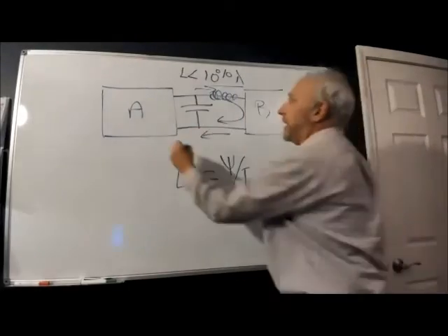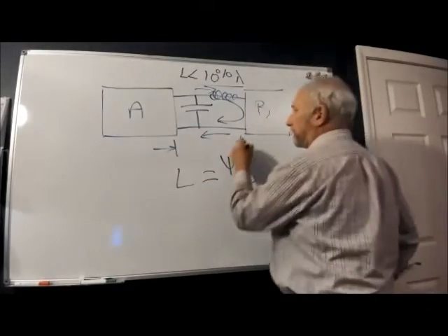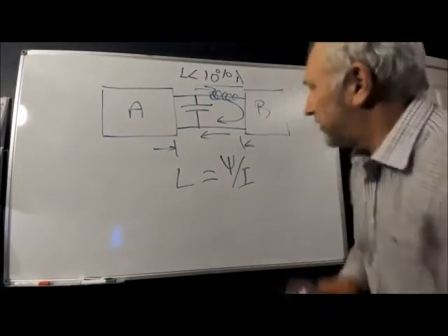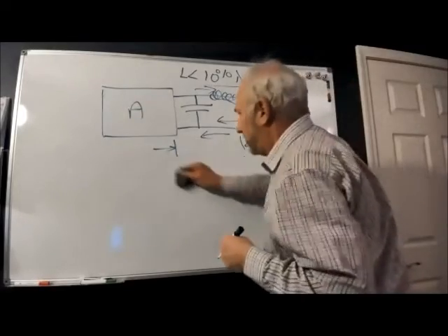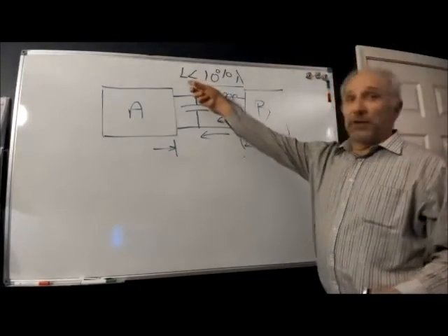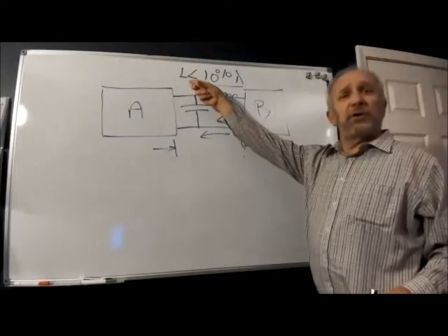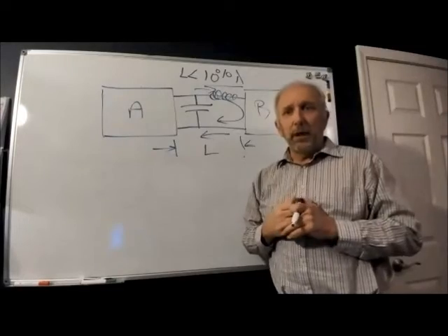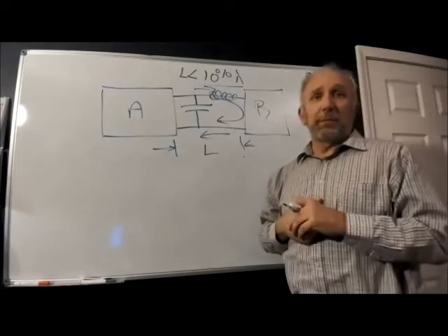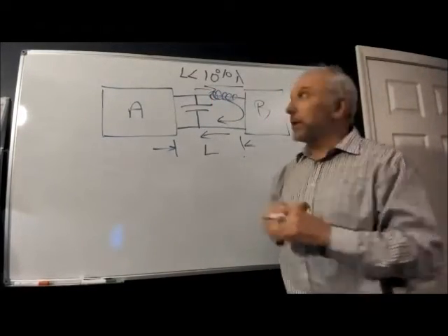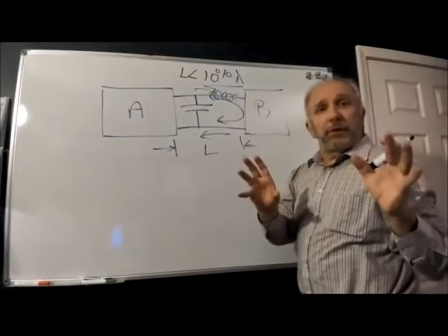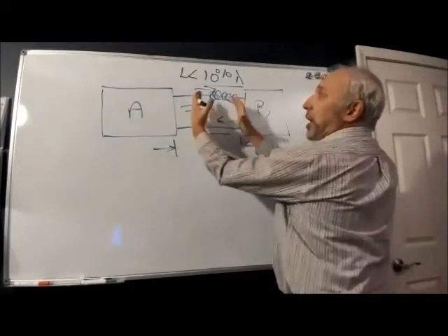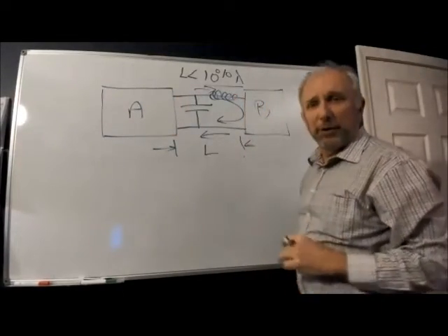When the physical length L, and by the way, these two L's are not the same, this L means the physical length. When the physical length L is less than 10% of a wavelength, we would say that we have this lumped model. Now, something interesting takes place. Keep everything else the same. This is the same circuit. All we're doing is moving those apart, spreading those apart.